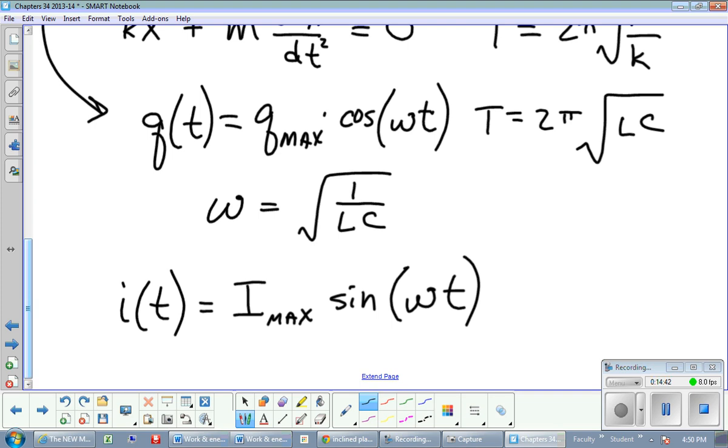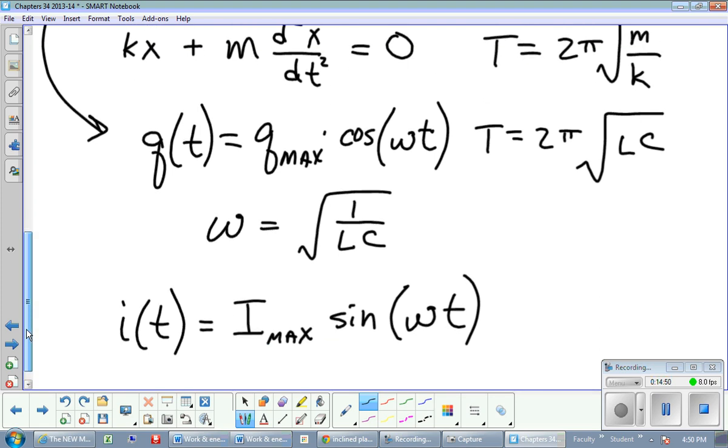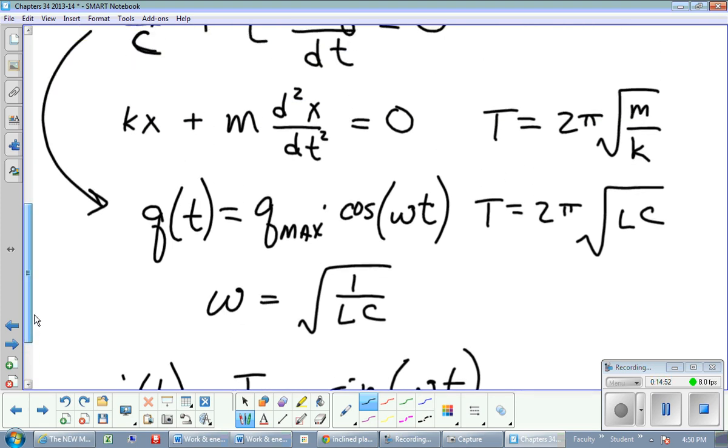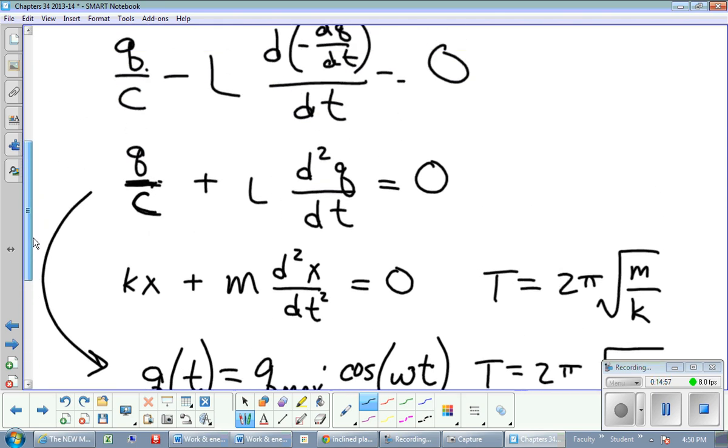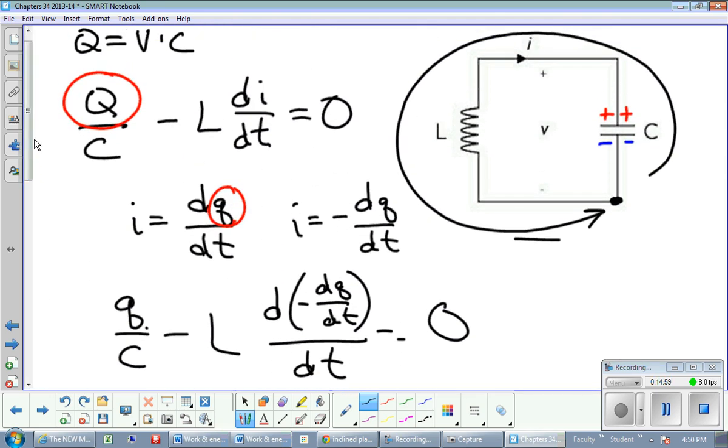So that's pretty much everything we'd want to know about an oscillating system. And it's a lot here. We know charge at any particular time. We might want to know current through the inductor as a function of time. We might want to know the period and how it relates to the inductor and the capacitor we're using. And so you can kind of see how we might use these as timing systems. There's other ways these are used, and I'll have to describe that maybe at another time. But these are the basics of the LC oscillator, and consult your book or maybe replay part of this if you need a little bit more. Hopefully that's been a little bit of a help for you.